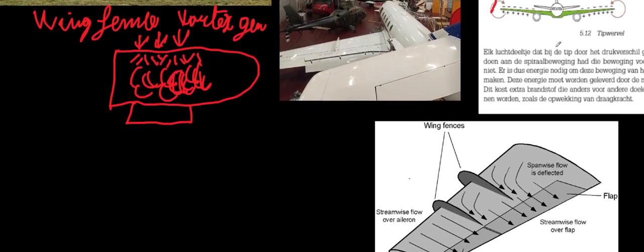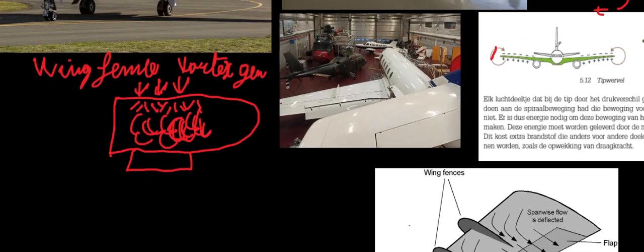Now, back to the wingtip fence. I'm also first explaining all of this so you get the wingtip fence at the end. The wing fence is not about making the aircraft more efficient, but it's about making the characteristics better. It's about making sure our aircraft stalls at a higher angle of attack, so you can actually do more with the aircraft. Now, higher angle of attack, I'll write that down because it's important to remember, it's actually the whole point of this thing.